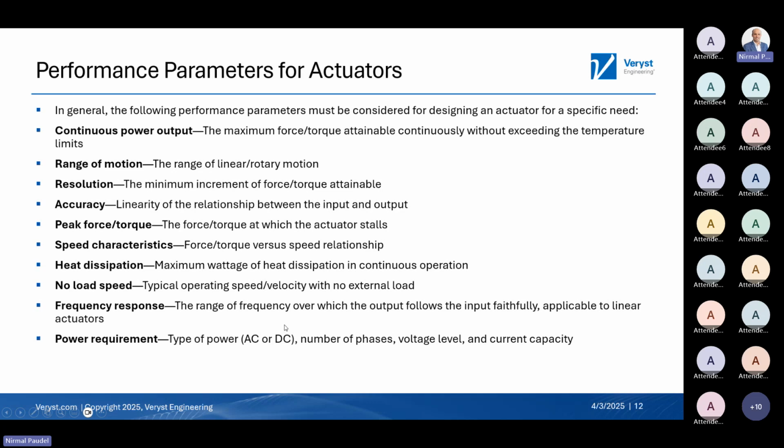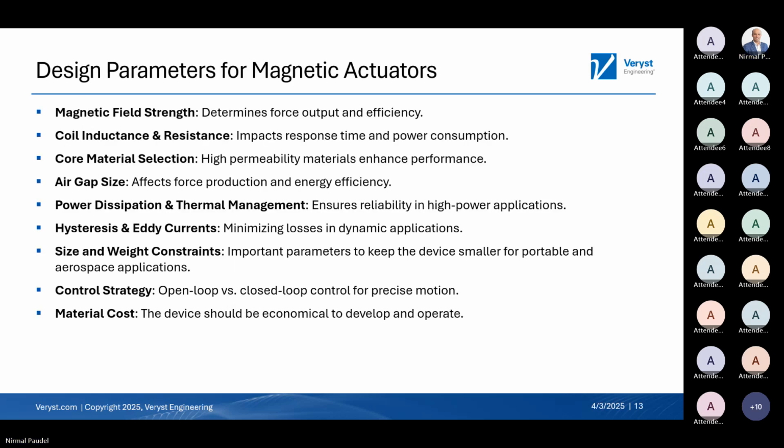And the frequency response, we have to make sure that we get the linear response throughout the frequency of operation, for example, in the voice coil or the vibration damping mechanism. And also the power requirements. Are we supplying DC supply or AC supply or multi-phase? What is the current level, voltage level, and so forth? So these are the performance requirements.